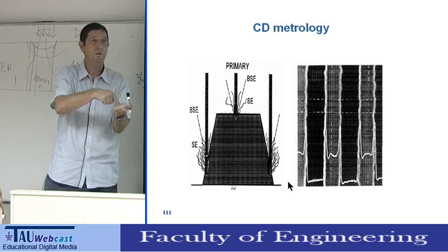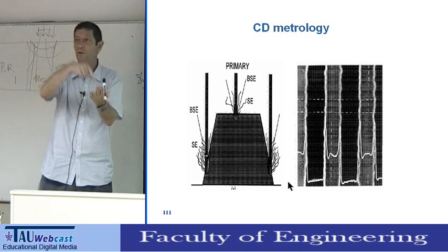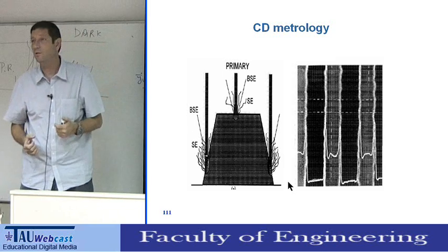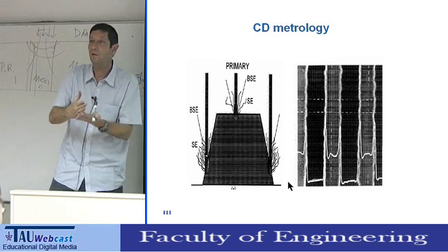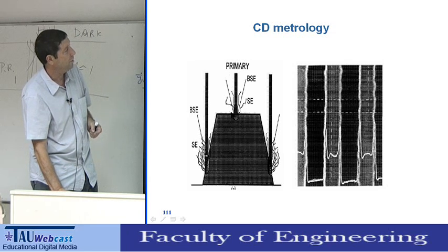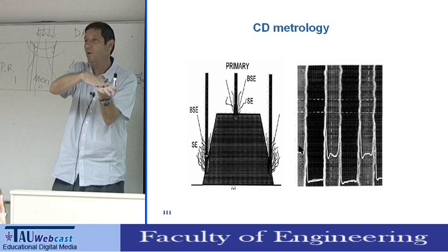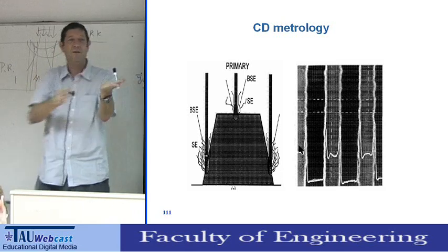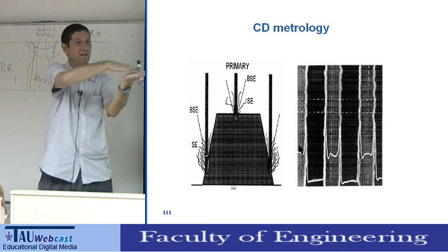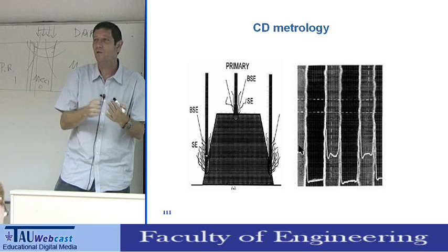So if you illuminate silicon with electrons, you generate X number of secondaries. If you illuminate photoresist, you're generating Y electrons. So you have a different signal, depending on the material. But the amount of secondaries also depends on the shape of the photoresist, because here you hit the photoresist perpendicularly, and here the electron is traveling and hitting at an angle. Typically when you hit at an angle, you generate more secondary electrons, because it's like throwing a stone on the water: you have longer interaction near the surface, and you can generate more electrons which come out.